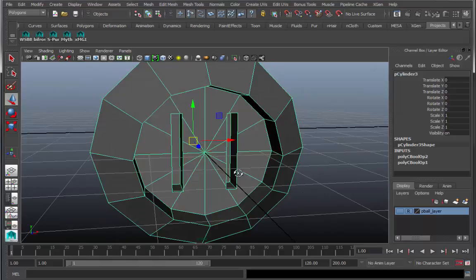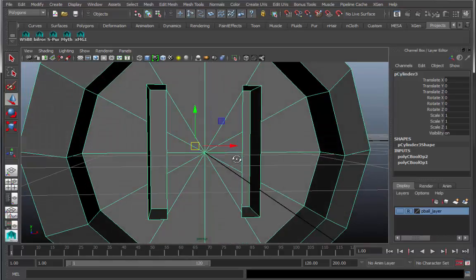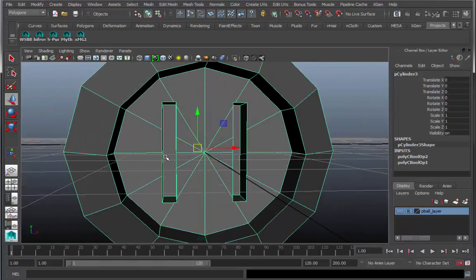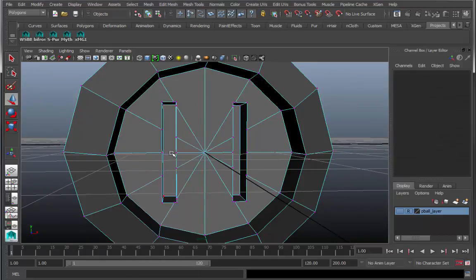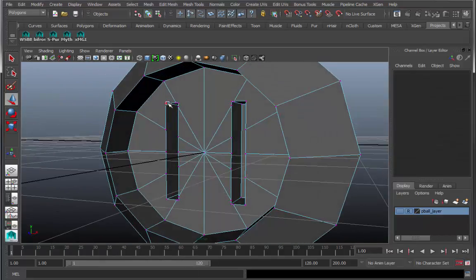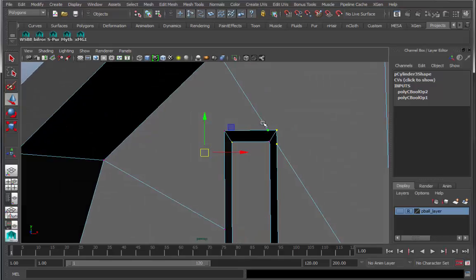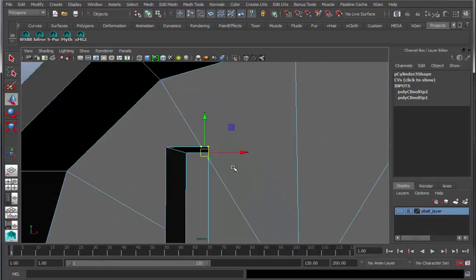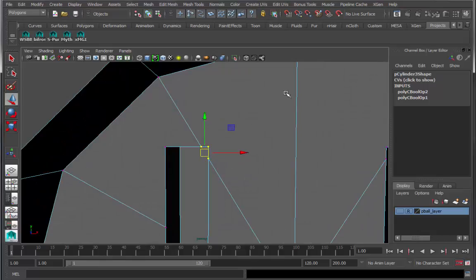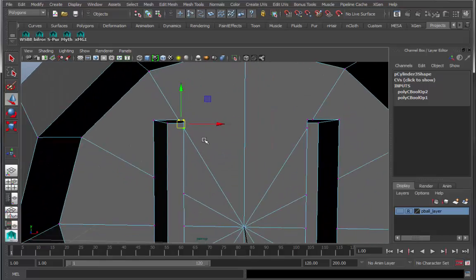Wonderful. So we need to resolve some issues here, which is that the Boolean operation has created dozens of little tiny vertices here. An example here is that it's done a pretty good job digging things out, but it has not optimized these vertices. So really now we've got a lot of extra geometry that Maya is going to create, because it's got to resolve all these faces into quads and triangles.